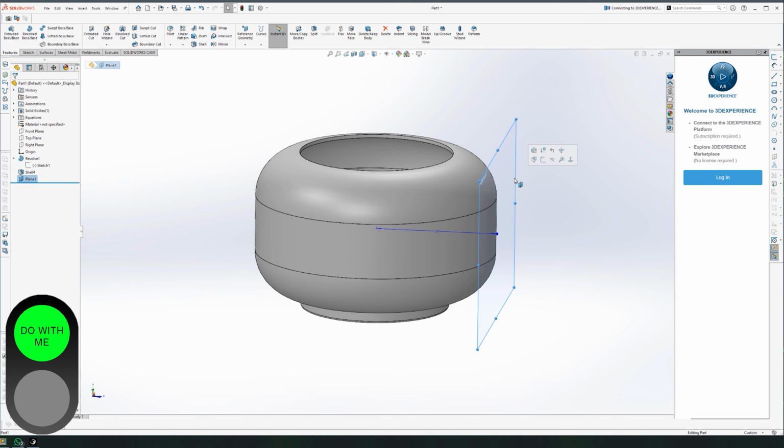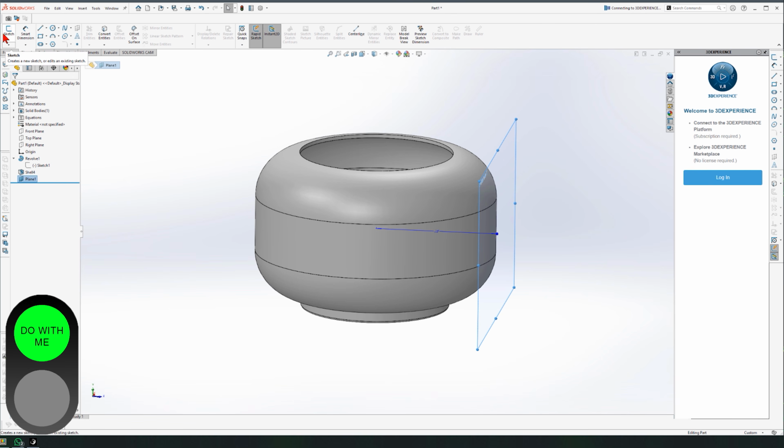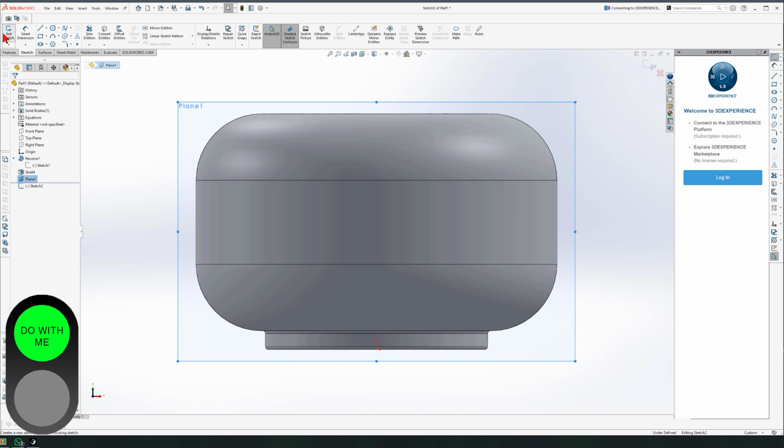Then we click on that plane. We go to the sketch tab and we click on a sketch. Then we are going to draw something oval, 44 by 33. And we have an oval tool here for it. Where is it placed? Like from the ground, it's placed around 19 from the bottom. So I'm gonna use this dash line as a help, not to place my point here or here. Just wherever this dash line appears, I'm gonna place my first point, go vertically up, and go a little bit right. That's all I did.